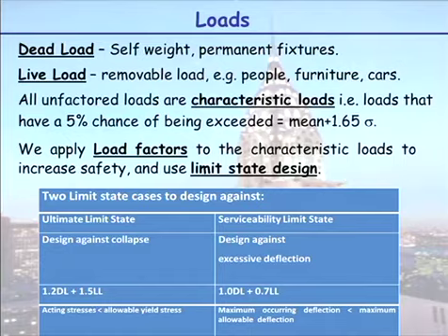So primarily things are designed for ultimate and serviceability limit state. One is designed against collapse, one is designed against excessive deflection. One has the bigger load, one has the smaller load. Now at this point, people say to me, but hang on a minute, Lizzie, this case is never going to be critical here because the loads are a lot smaller. What you will realise when you work through the procedure is that when we say we have two different designs, we actually do two different checks on them.